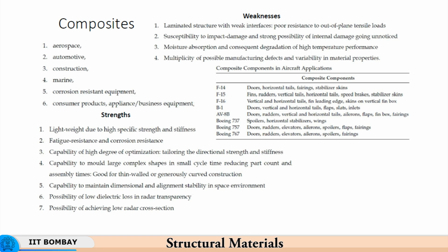So you have many strengths as given here, and that makes it applicable under a wide variety of circumstances. However, there is a word of caution here. For example, moisture absorption becomes a problem at high temperatures, and there is degradation at high temperatures, and a multiplicity of manufacturing defects which one has to guard against. So these are some of the weaknesses which one has to take into account.